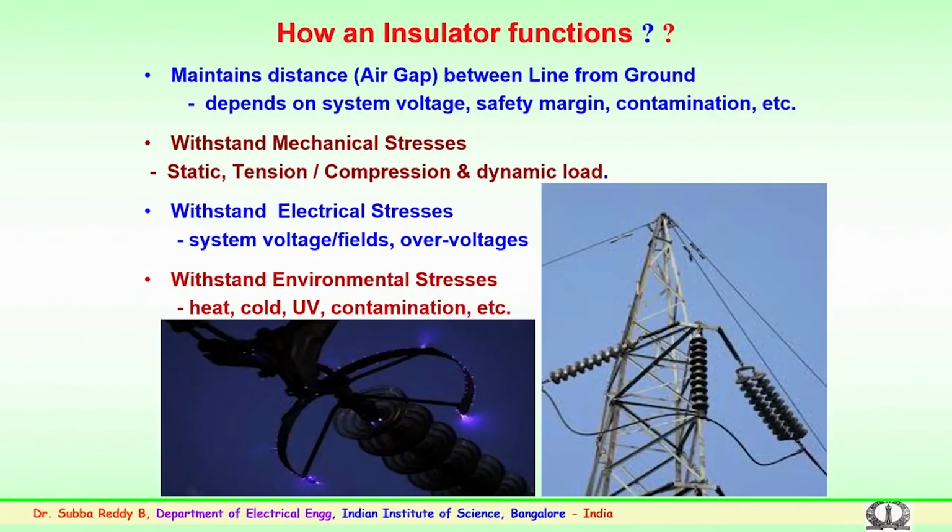Over voltages could be because of the lightning effect, where lightning strikes the tower, and proper shielding or a ground wire protects it. In case that is not able to protect it, over voltages because of lightning could be induced, and these travel to the substations, and the equipment in the substation could be damaged, or the insulator string could flash over because of this lightning effect.